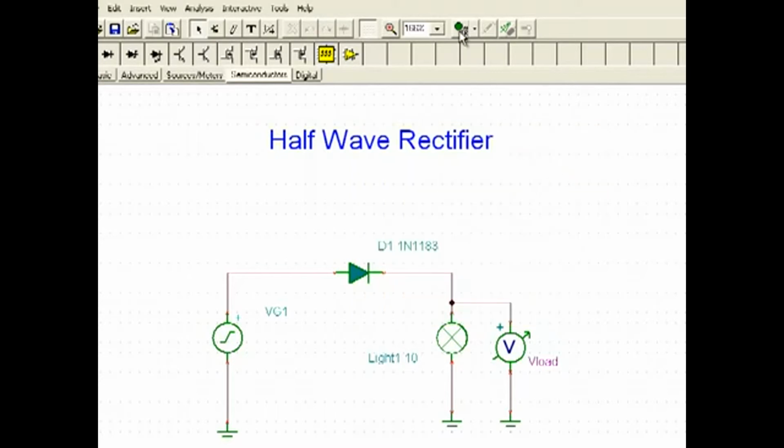So we'll run the simulation, 1,000, 2,000, 3,000. We can see that our bulb is flashing roughly once per second. Let's take a look at our circuit again in analysis mode. I'll turn off the simulation. We should note that there's a voltmeter at the output here called V load. That'll help us identify the output waveform in the analysis.